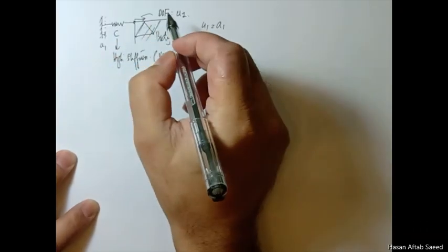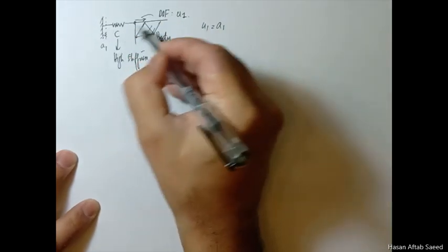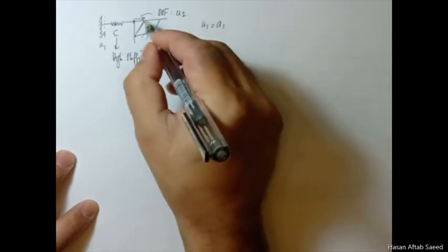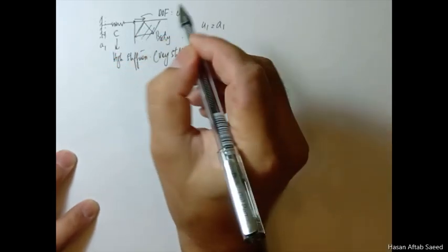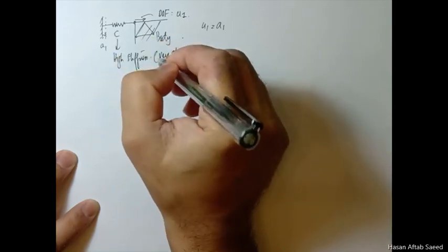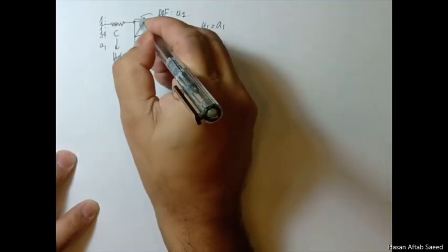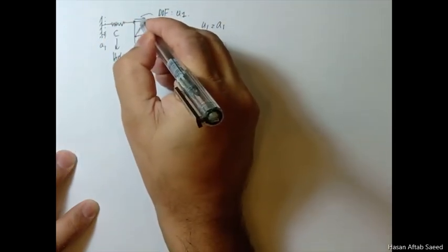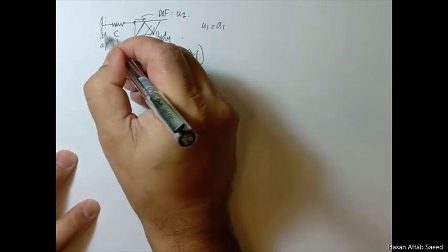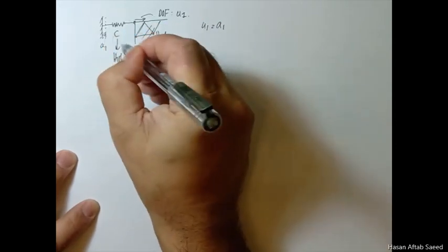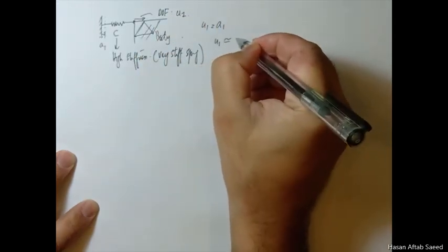Now, because this spring is a very stiff spring, if it was of infinite stiffness, it would have been a rigid bar. So in that case, a1 would have been equal to u1 applied here. You would have been able to apply a1 here also. But although it is of a very high stiffness, it is still not a rigid bar. So there will be some sort of compression here, and the displacement that you'll be able to apply here will be slightly different from A1. Okay, so you apply the A1 here instead, so you end up applying a displacement boundary condition which is actually very nearly equal to A1 but not A1.